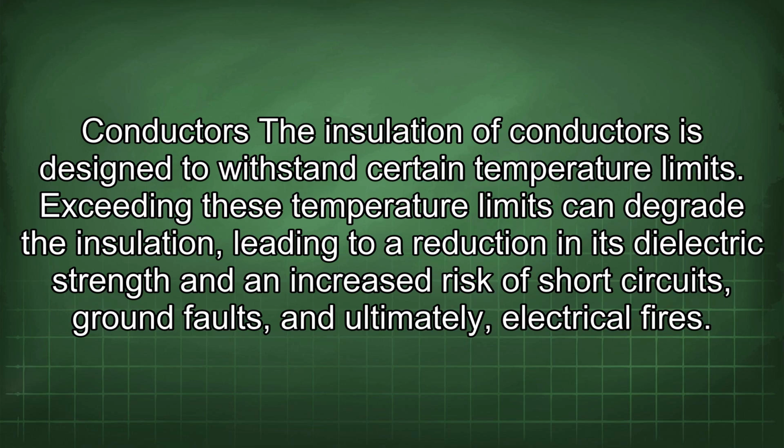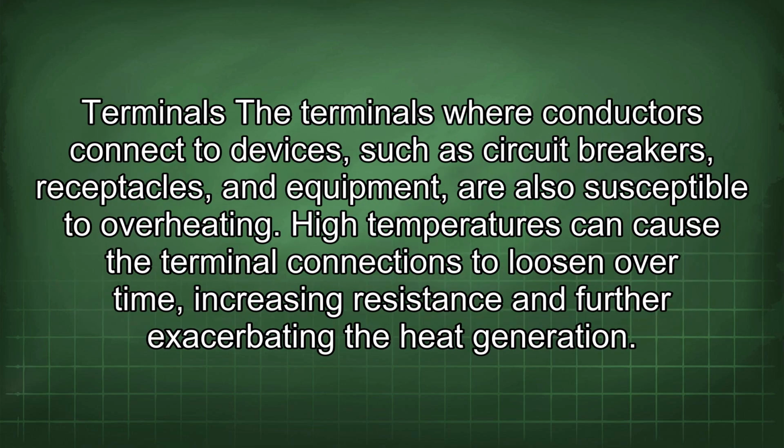Conductors. The insulation of conductors is designed to withstand certain temperature limits. Exceeding these temperature limits can degrade the insulation, leading to a reduction in its dielectric strength and an increased risk of short circuits, ground faults, and ultimately, electrical fires. Terminals. The terminals where conductors connect to devices such as circuit breakers, receptacles, and equipment are also susceptible to overheating. High temperatures can cause the terminal connections to loosen over time, increasing resistance and further exacerbating the heat generation.